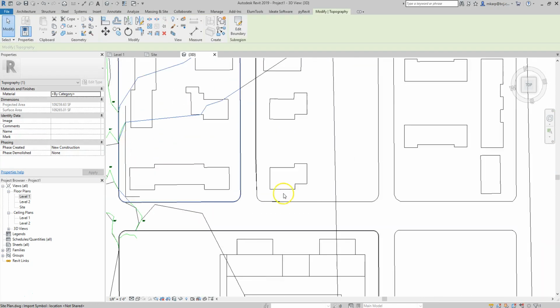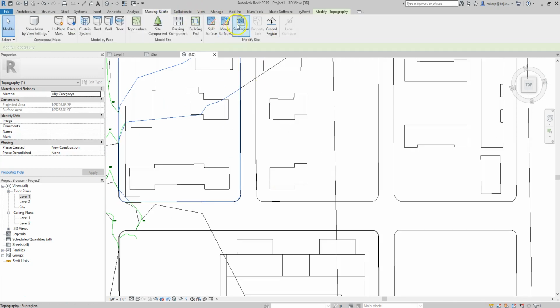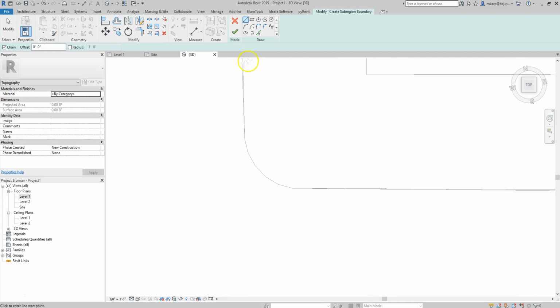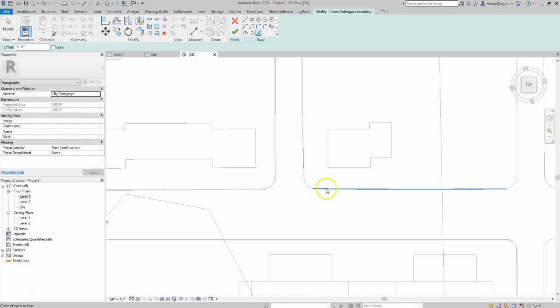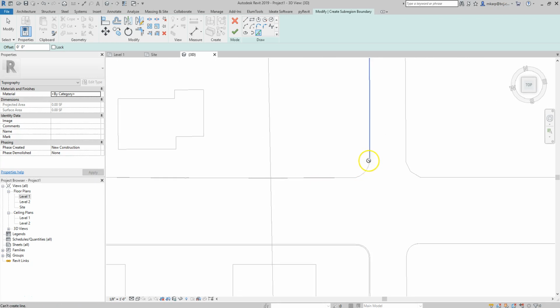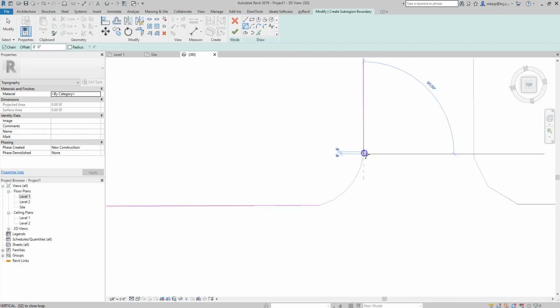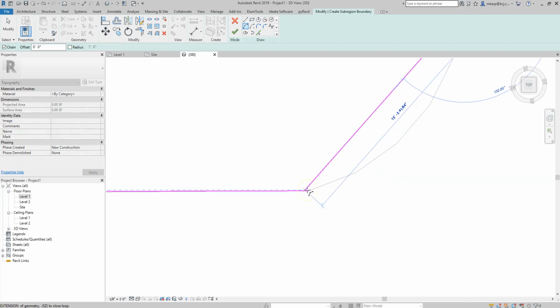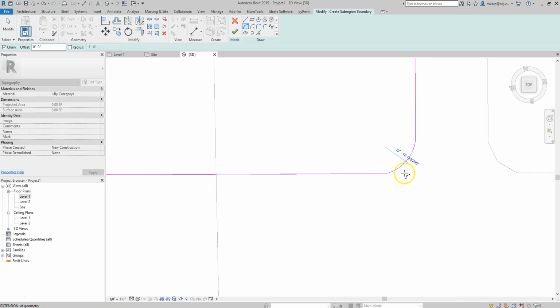Okay. So what happens when we're doing this is the beginnings of a pretty common command in Revit, which is kind of the profile drawing command. This one's going to be a pain, isn't it? It's how you would make floors and roofs and things like that, is you draw these pink lines. You can tab through and make sure you select what you want selected.